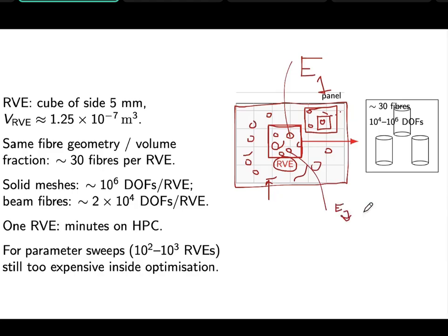but you don't know exactly what E1, E2, and so on are, because, as we said before, they are parameters, and we measured them in the warehouse, and we did all of that, and we don't know what the temperature was. We don't know anything. So all these parameters have statistical distributions, but we're not exactly sure what they mean. We don't know the mean. We don't know the standard deviation very precisely. So we need to do some parameter sweeps in order to make that clear. And so we need to sample the distribution, use Monte Carlo analysis.